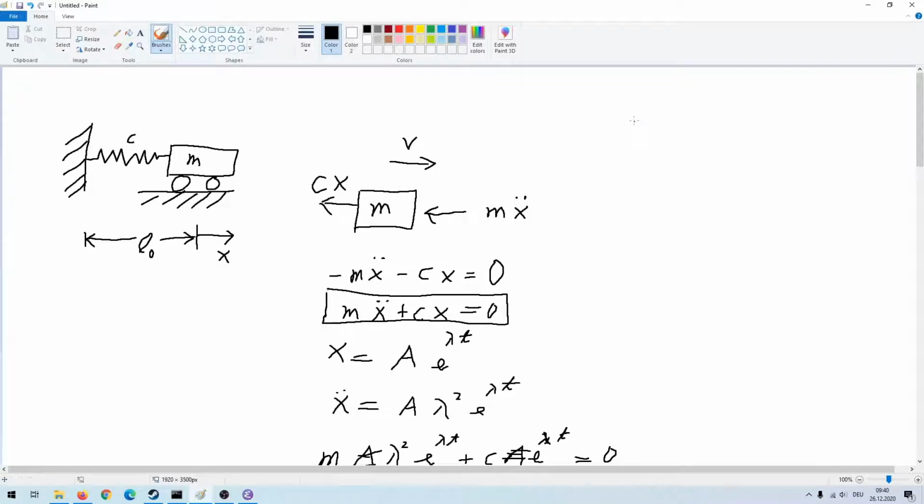that. So if we assume this is our time and this is our, slightly wrong, this is our displacement. There is a formula called, of course, the explicit Euler. And explicit Euler is basically a way to extrapolate and to compute the next step in time numerically.